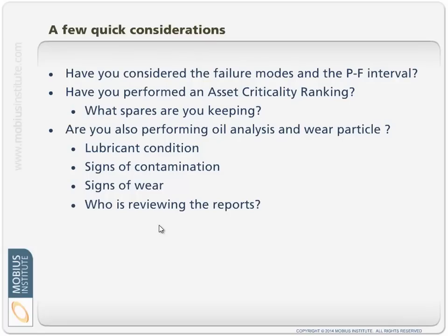So the earlier you detect it is always a good thing, but you've got to think about the PF interval, and if it happens to be short, then you need to be monitoring it much more frequently. If it's a longer failure mode, then you've got more time, but of course you've got to consider all the failure modes, and whatever is the shortest, that's going to determine how frequently you take your measurements.